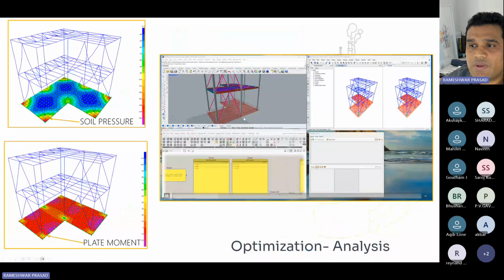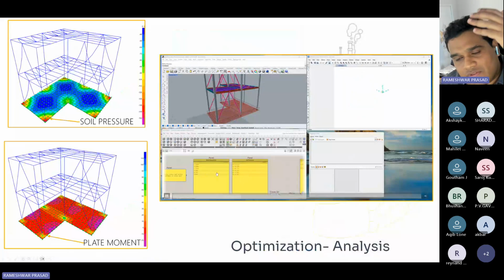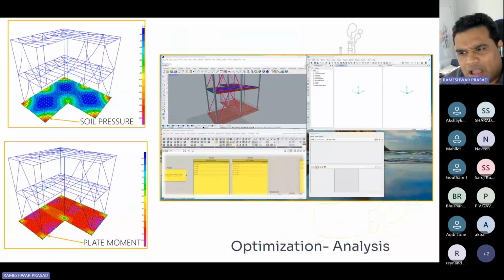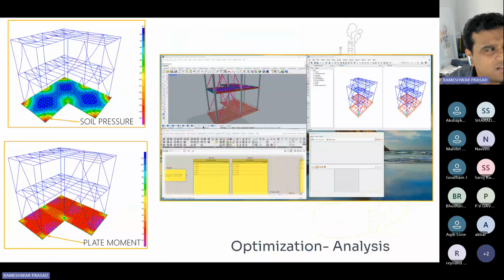So what we did was predefine a few mesh sizes, and we recorded the soil pressure for every mesh size. Although we have restricted the video to 3 or 4 over here, we gave around 15 or 16 such options. So 100, 200, 300, 400, 500. And then you'll start noticing that the soil pressure won't change beyond a certain mesh size, and that is the optimal mesh size that you can adopt for your model.